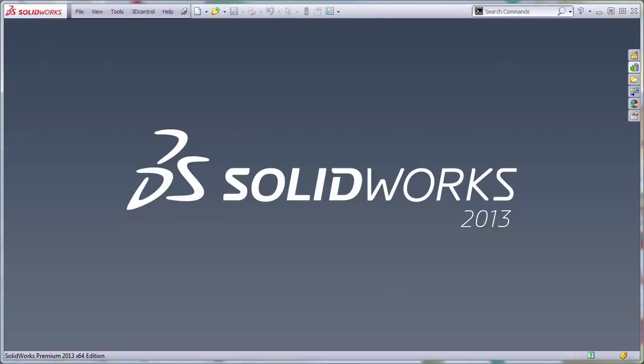Welcome to Lesson 2, Customizing SOLIDWORKS. In this lesson, we'll learn how to customize the toolbar visibility. We'll learn two ways to add commands to a toolbar. We'll customize our system options. We will customize document properties. We'll save our customized template. We'll set up file locations, and we'll also customize the SOLIDWORKS add-ins that we want to use.